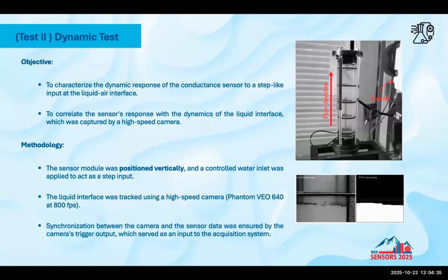Okay, moving on to our second test. It's a dynamic test. Here we have another interesting parameter, the dynamic response of the conductive sensor to a step-like input at the liquid-air interface. We put the sensor vertically and apply a step input formed by the liquid interface.